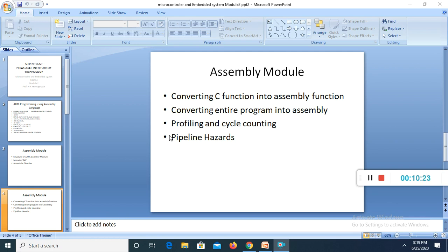The library request makes a request, which we write in programs, that the linker links with the standard ARM C library. The WEAK specifier prevents the linker from giving an error if the symbol is not found at link time; it will take the value 0. The second imported symbol, main, is the start of the C library initialization code. Importing printf allows us to call that C library function.